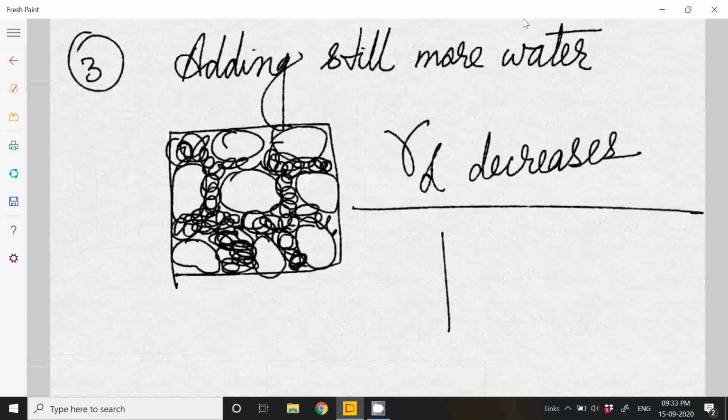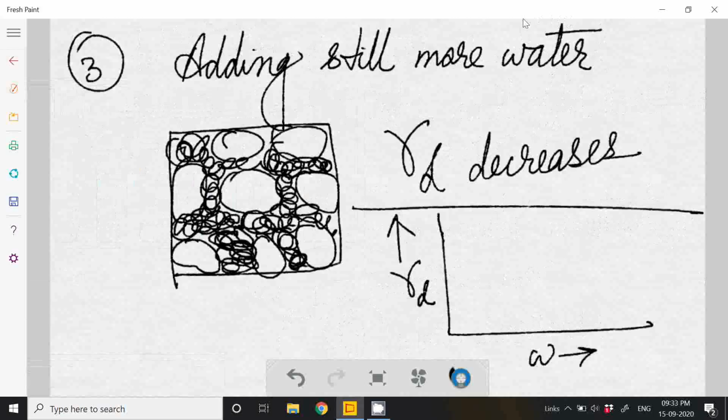So this is the basic story. If I keep adding water content, and you look into the dry unit weight, which signifies the compaction, then at the very beginning there will be lubrication, particles will start rearranging themselves into a denser configuration, and the highest level of compaction will happen at one point, meaning high dry unit weight. From here onwards, stage 3 will start.